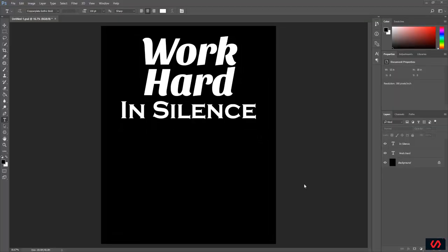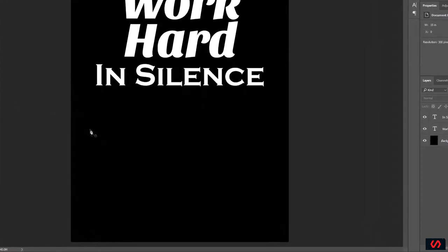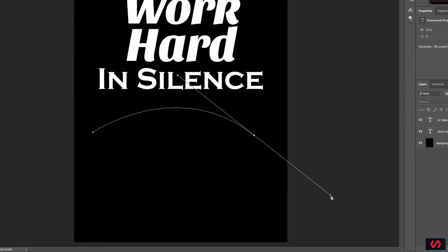In this video, I show you how to create text that follows a specific path. To do this, from the left panel, click on this pen tool and on the canvas on the left side, click on this one time and drag your cursor to the right and click here and hold it down like this. Once you have a line similar to this, you just release your mouse.